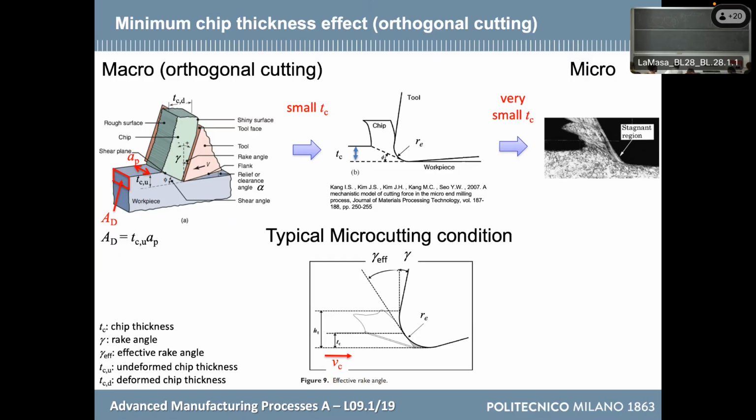But now, let's focus here. In a case like this, the forces are just bidimensional because there is a certain angle of the cutting edge with respect to the material. For example, this angle here is perpendicular to the cutting speed. So if you imagine to take the cutting edge, there is no angle on this plane, but the direction is perpendicular to the cutting speed. It goes like this, so there is not an angle like this. Because you can imagine that if I have an angle here, the chip, instead of sliding this way, parallel to the cutting speed, would slide a little bit to the right. If I do this way, the chips will flow in this direction. Instead, we don't have it.